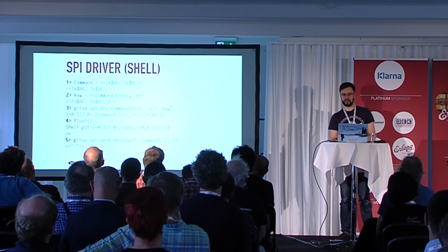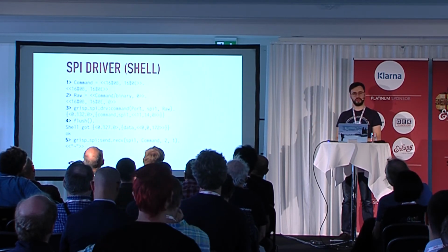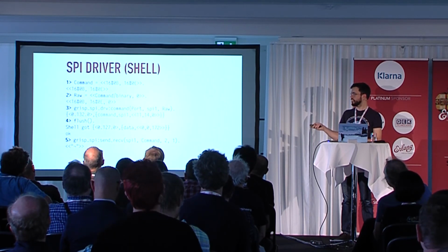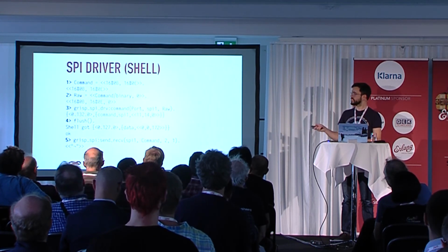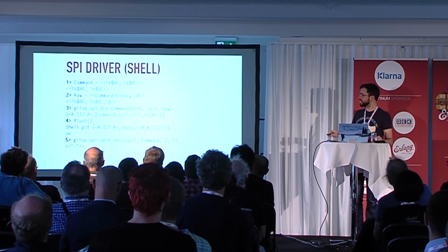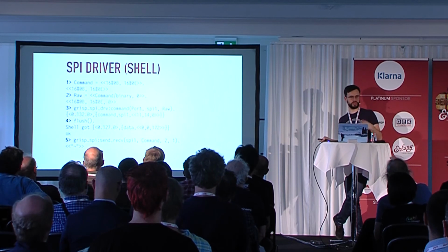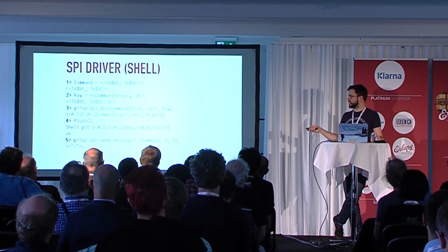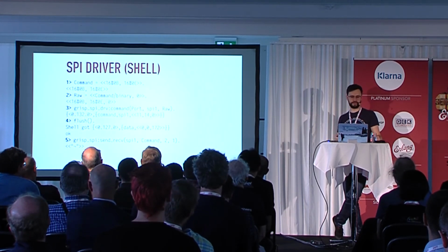If I send this as a message to the port, and then I just flush to see what I got back, you can see that we got some data back. So in the end, we sent 3 bytes, and we got 3 bytes back. I was nice enough to send nothing in the third one, because I'm not really caring about this. And the PMod was nice enough to send nothing in the first 2, where my command bytes were shipped over, because it wouldn't know what to send there, right? And then as the last byte, I get the value back from this register I was asking for.